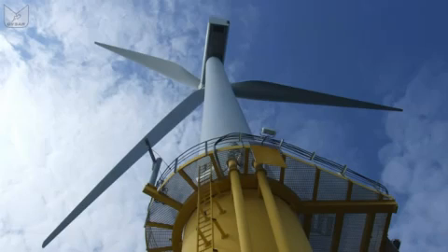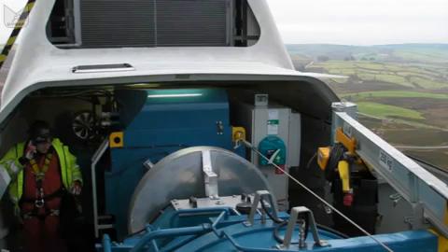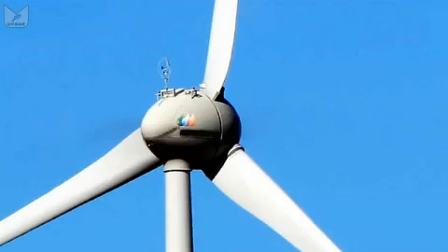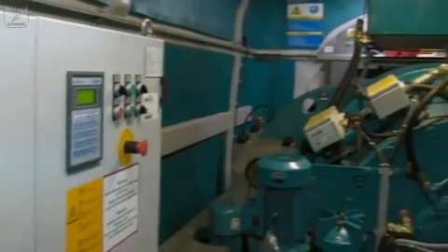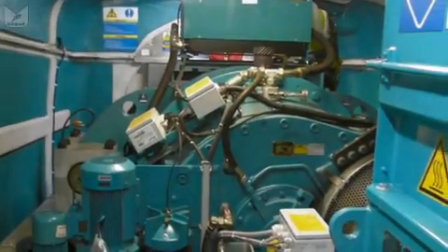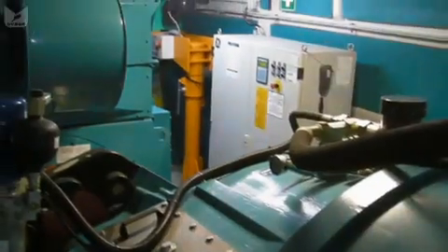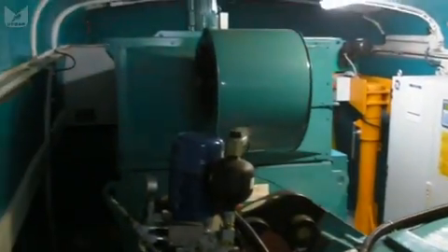The layout of a multi-megawatt nacelle is again more variable than for a smaller version. We always have to have a generator, but we may not have to have a transformer. In a few cases, such as the famous Enercon egg-shaped nacelle, we don't even need a gearbox. They're direct drive. We just have a shaft linking to a motor, and then lots of extremely complicated electronics to condition that power for connection to the grid. But in most cases, we need the same as we needed in the small turbine: gearbox, generator, possibly a transformer, all in a fiberglass box.